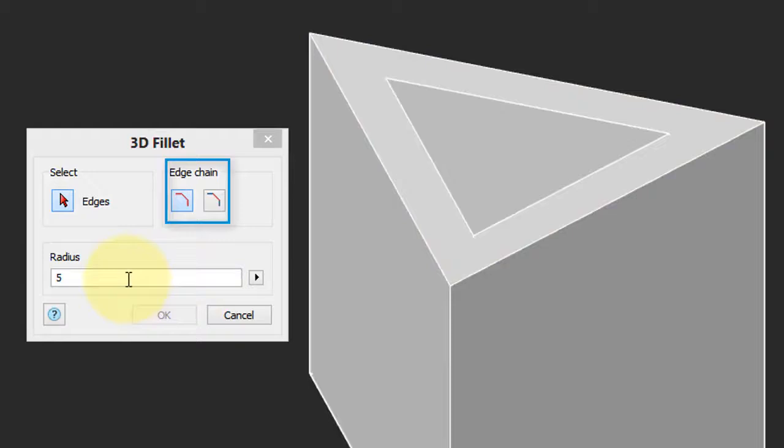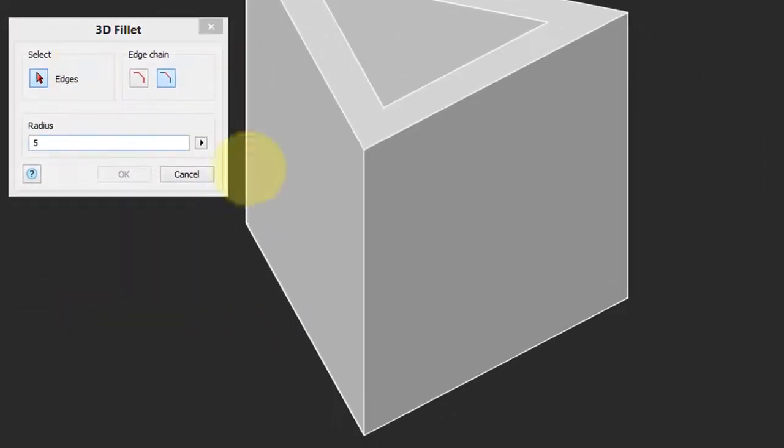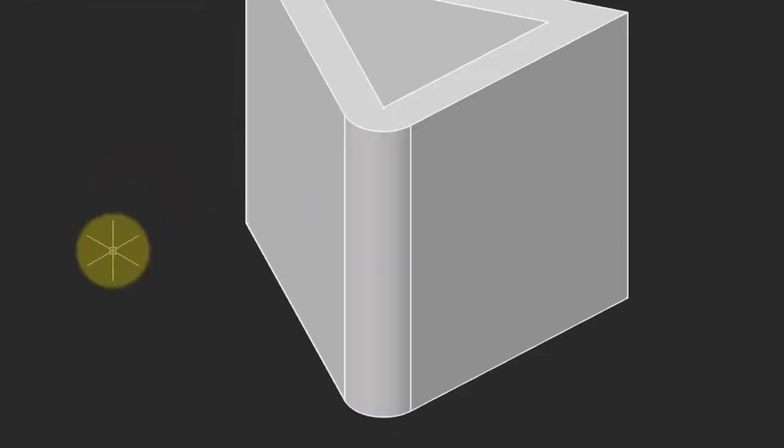There's 2 different ways to fillet a solid. First we'll do the Select Single Edge. Here's an important thing. Ignore this area of the dialog box. Now go into the drawing and select an edge you want filleted. Notice that nanoCAD highlights it in green. I'm going to select it, and then in red nanoCAD is highlighting how big the fillet will be. Sometimes it's possible to have a fillet that's too big and then nanoCAD won't add it to the model. Click OK and the fillet is added.